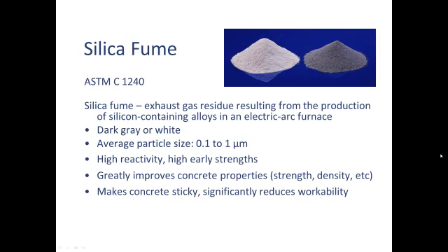I've used silica fume in the past. I've blended it. You can blend. The great thing about pozzolans is you can blend them. Now, getting into blending means you're starting to delve into a world of, are you changing things and is it getting any better? One pozzolan is perfectly good. Three just makes it more complicated. It's not necessarily going to make it better for your customers.